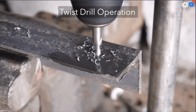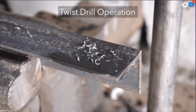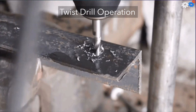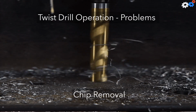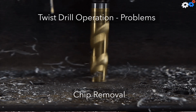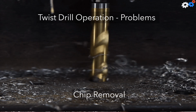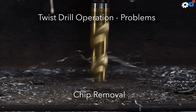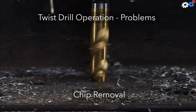The relative velocity of the drill point is zero, so no cutting takes place. Instead, a large thrust force is required to drive the drill forward into the hole. The chip removal represents the main problem we have with the twist drill operation. The flutes must provide a sufficient clearance to allow the chips to move from the bottom of the hole during the cutting, but the friction makes the matter worse. The delivery of the cutting fluid to drill points to reduce the friction and heat is difficult because the chips are moving in the opposite direction.